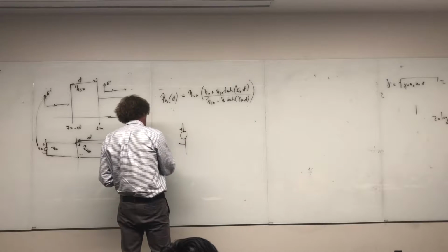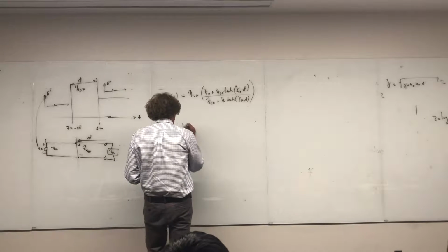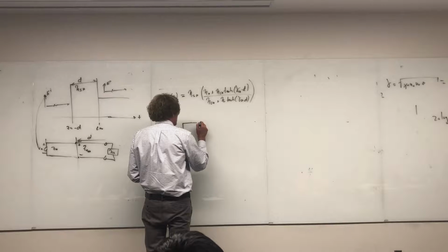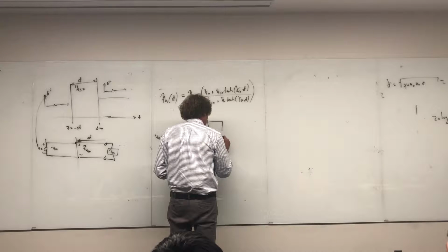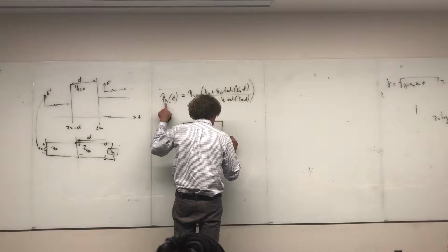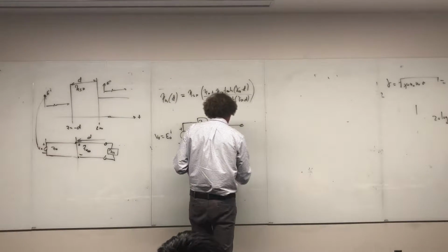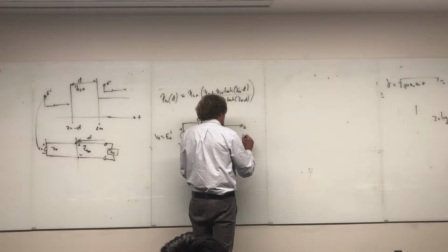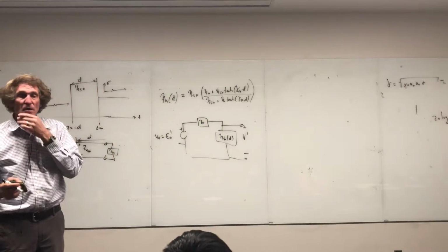Now we're going to have this V naught right here is actually equal to E naught incident, and it parallels that. Then you're going to have a characteristic impedance here of just Z naught, right? I mean, that's going to be in series. And then you're going to have eta of the, really the input of the shield, eta n here of the shield at a distance d. And you're going to find this value of voltage. You're going to have plus to minus, and I'll call it V prime. Follow me on this? That's just like when we did the transmission line problems with the lossless case.